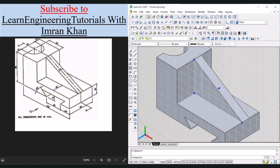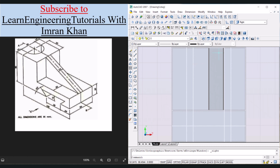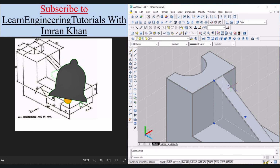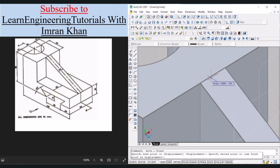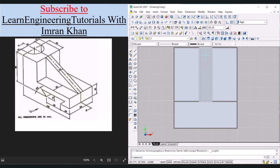Now we have to move this object because this is misplaced, as can be seen from the right side view. You can see that this is not centered. So click on isometric view, zoom in. Now we will click on this object, click on move. We have to specify the midpoint of this object and then place it on the midpoint of the first object. So here we have to click. Now the object is placed. Let's visualize this in the right side view, and we can see that this is now in the middle.